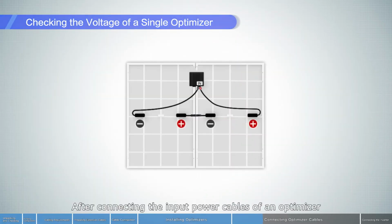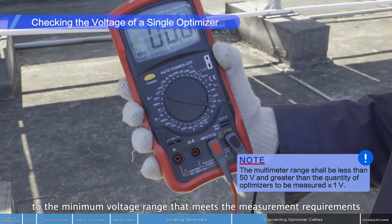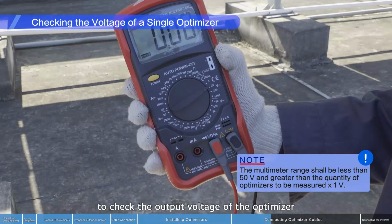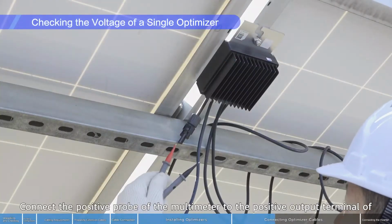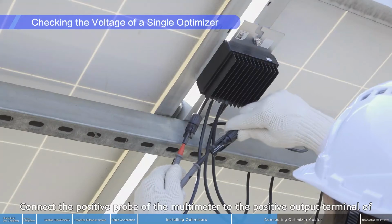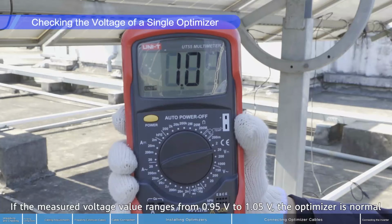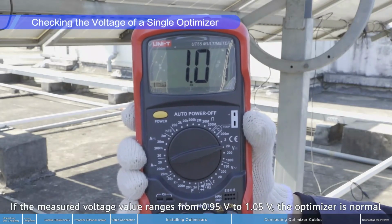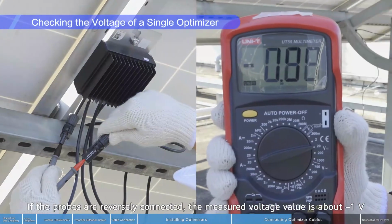After connecting the input power cables of an optimizer, set the multimeter to the minimum voltage range that meets the measurement requirements to check the output voltage of the optimizer. Connect the positive probe of the multimeter to the positive output terminal of the optimizer and the negative probe to the negative output terminal. If the measured voltage value ranges from 0.95 volt to 1.05 volts, the optimizer is normal. If the probes are reversely connected, the measured voltage value is about -1 volt.